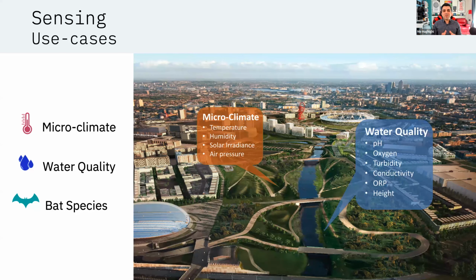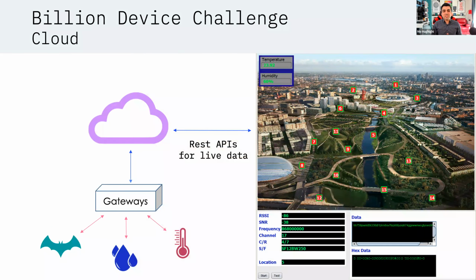So all these sensors, we connected them to these Edison devices, and we spread them around the park. And then we had the gateway. As I said to you, that gateway was a LoRa receiver on top of the orbit to capture all these signals coming from these devices. And then it was connected to a cloud where we could read all the data coming in, in real time. That was quite interesting, because we had all these devices across the park. But sometimes, because of the noise in the park and people walking around, we had a lot of dropout in the signal and blind spots that we had to solve.